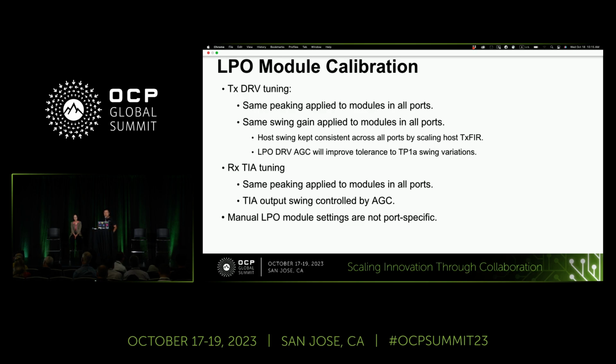Now, with the AGC of the LPO driver, it will improve the tolerance to the swing variations. RX TIA tuning is relatively straightforward because it's already implemented in the retimed module.